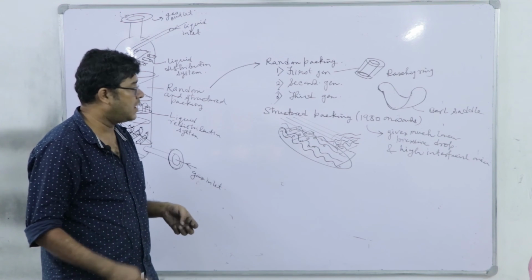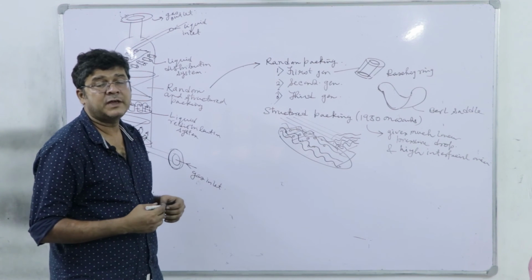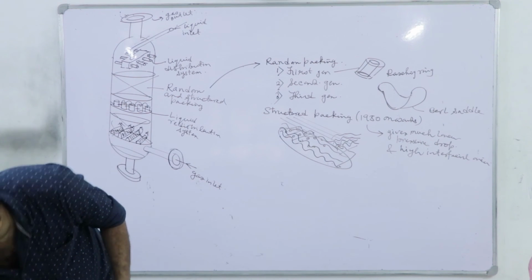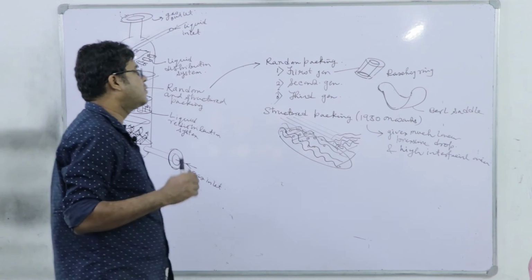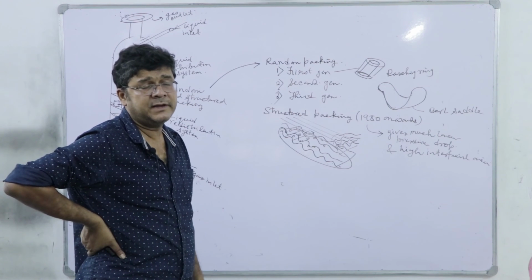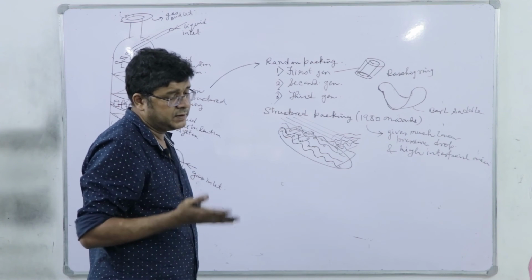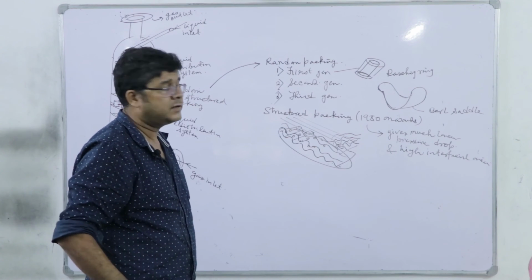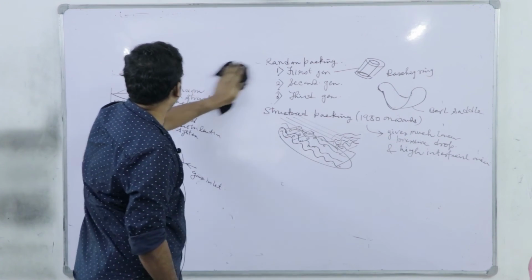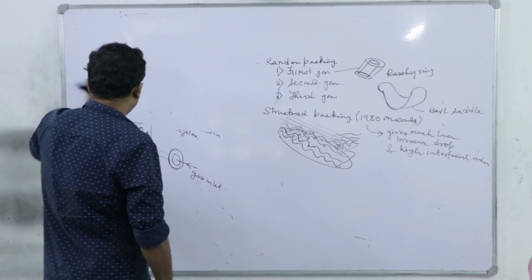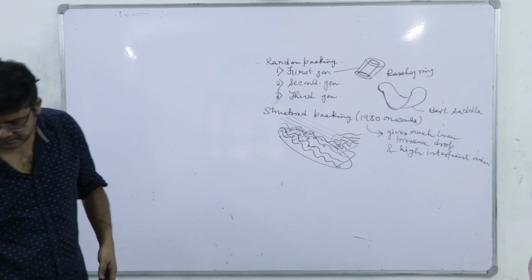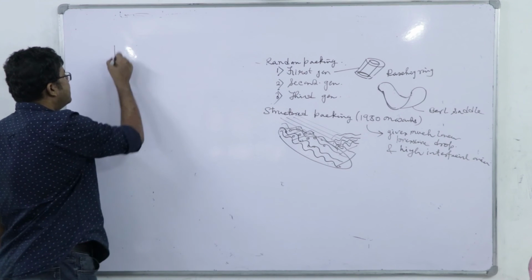Now, similar to tray column, here also in packed column we have the non-ideality of flooding. So, what is flooding here? Here you see that as you go on increasing the gas velocity, the liquid flow will be highly impeded, right? And the liquid will start accumulating over some region of the column at a specific gas velocity. And this we generally try to understand through a log-log plot of pressure drop and the gas flow rate for different liquid flow rates. So, here what we plot.